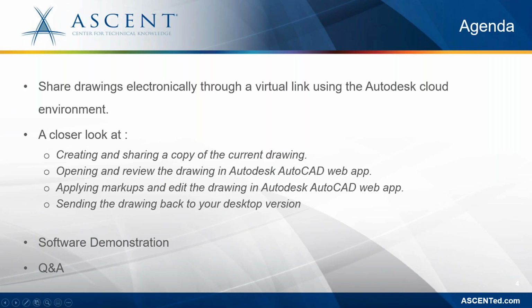So let's begin with today's topic, which is to share drawings, and this is a new feature that was introduced in AutoCAD 2022. What it does is we share drawings electronically through a virtual link using the Autodesk cloud environment. So if you're on the go, or if you want to share with people who do not have the desktop version of AutoCAD, you can share the link with them, and they can do light editing or mark up the drawings in the AutoCAD web app.